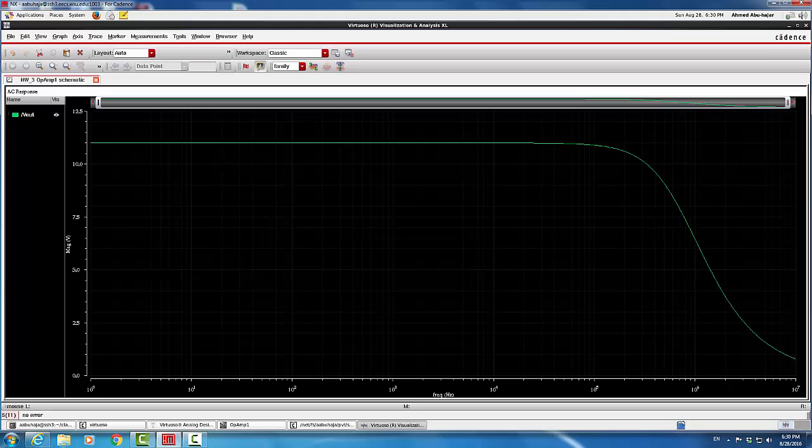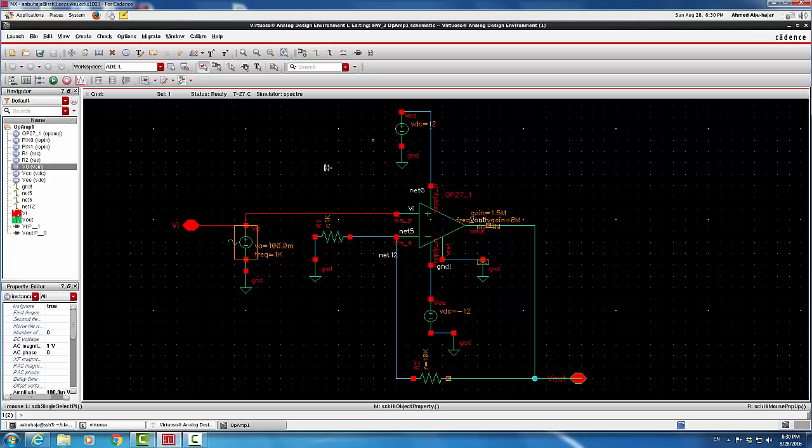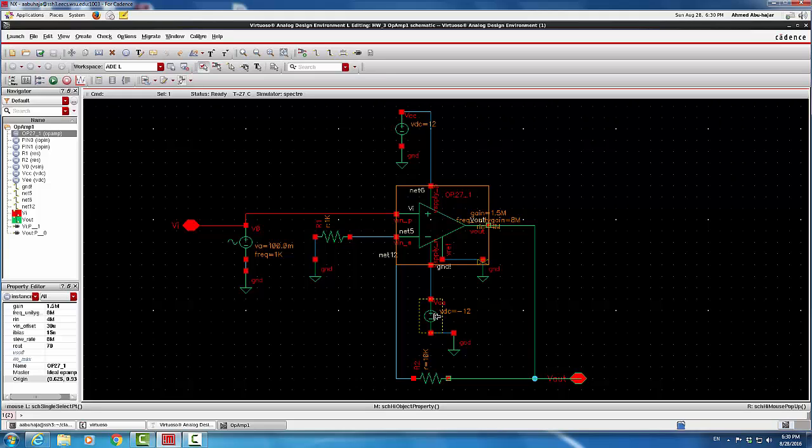What's interesting is, this is what I wanted you to see from this simulation. In this simulation, as you can see, we don't have any capacitors or inductors in the circuit. We have an OpAmp. We powered the OpAmp with DC voltage sources, and we have two resistors, R2 and R1, that will go around the loop, right? You know, a typical non-inverting configuration.